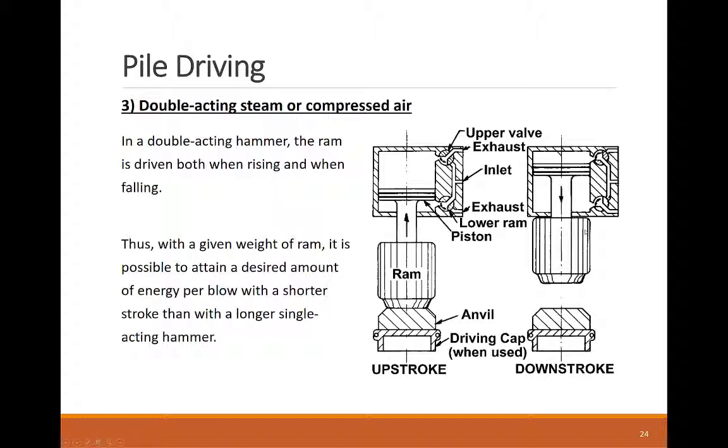The double acting steam or compressed air hammer can be improved by using the compressed air or steam to create differential pressure in both ways, lifting and dropping the ram. This delivers more driving power with the same input of energy.